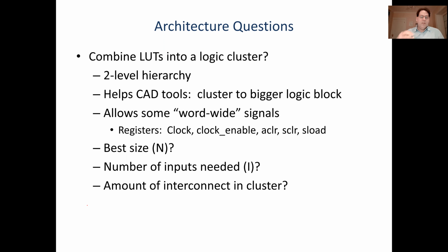Okay, so other questions. Should we combine lookup tables into a logic cluster? I already talked about this. That forms this 2-level hierarchy. It helps your CAD tools. It allows some word-wide signals like clock and clock enable, which don't need as much flexibility, to be shared across the whole logic cluster. The logic cluster gives us a natural way to do that. We talked about that a couple of weeks ago. Lots of good reasons to do this.